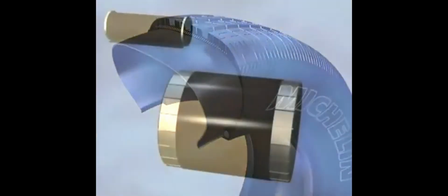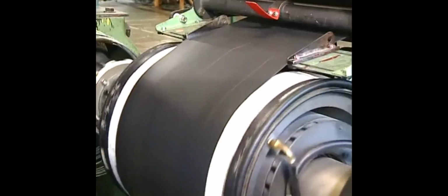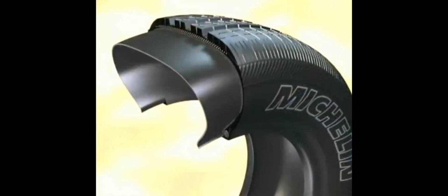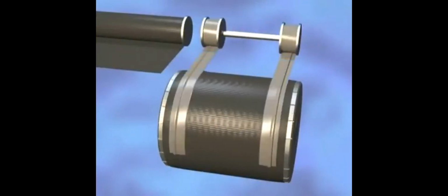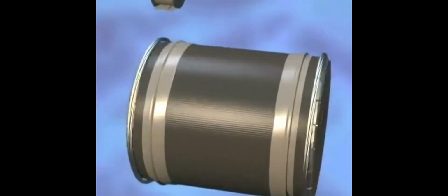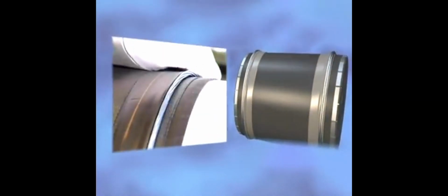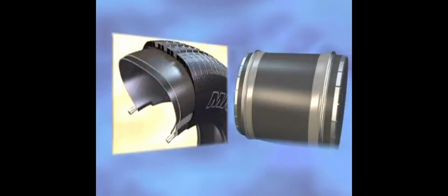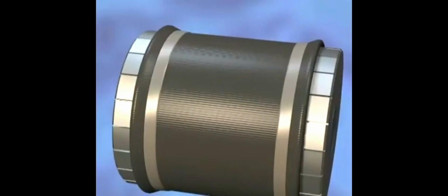The second layer is called the casing ply. Why? Because it contains the framework of parallel fabric cord, which we call the casing. This assembly is the vital substructure and consequently a key component in the radial tire. Set tightly against strips of profiled rubber are two high-resistant steel wire hoops, which are known as the bead wires. They hold the tire firmly on its rim. The casing ply is then folded up over the bead wires to hold them securely in place.